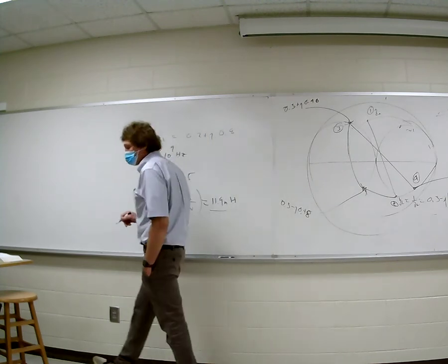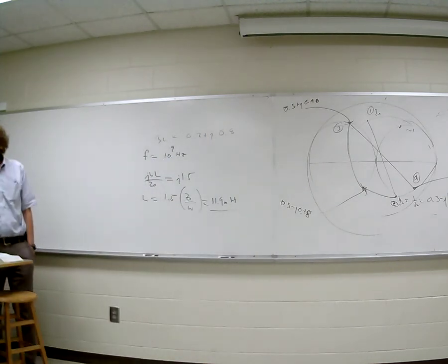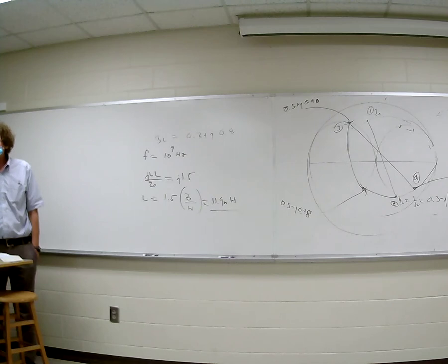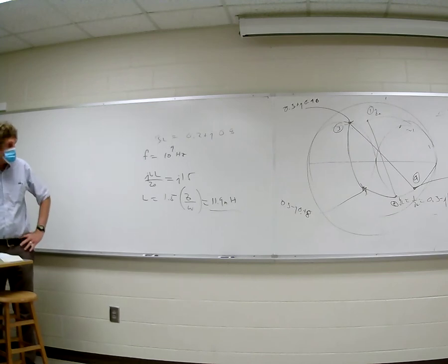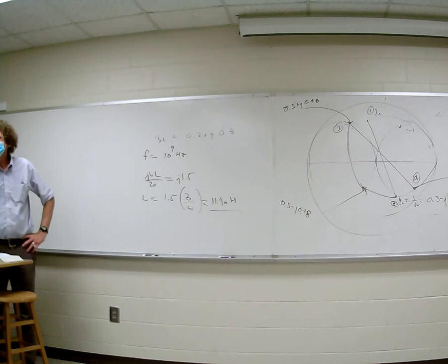Now that's small. Those values are small, but they're available. One of the things you're going to find when you're doing this is that a lot of times an 11.9 nanohenry component may not be available. So you would probably get a 10 nanohenry, and then you would just mess with the lead lengths a little, so you added that extra bit, and you can measure the impedance of that with a spectrum analyzer. This would be more laboratory work, but you can measure these things with good equipment. Have you worked with network or spectrum analyzers?